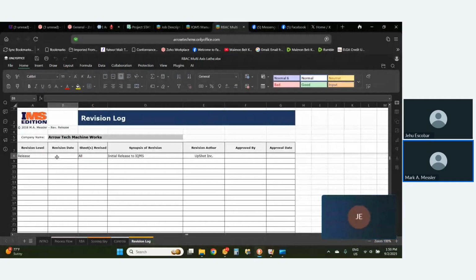Okay, don't forget to fill the revision table in. So in this case, since I made changes to it, what would I put there in the revision level? Well, because you haven't officially released it yet, you can make as many changes as you want. Until you actually finish it and get all these things filled in, if you make a change after that, then you would log it.